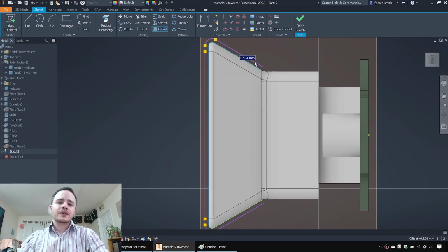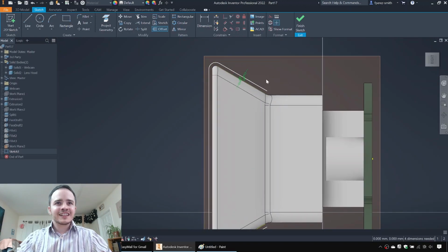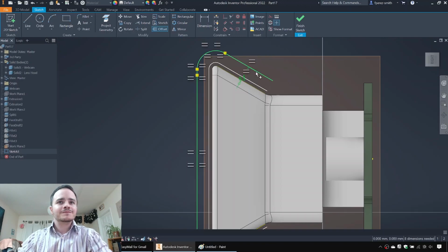And this time it doesn't need to really fit in snugly there. So we're going to give it 0.5 mil of clearance so that it's nice and far away from it. We're going to add in our thickness now. And we are going to say that the thickness of the cover is 1.7 mil.